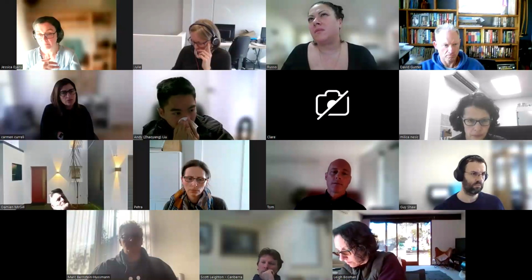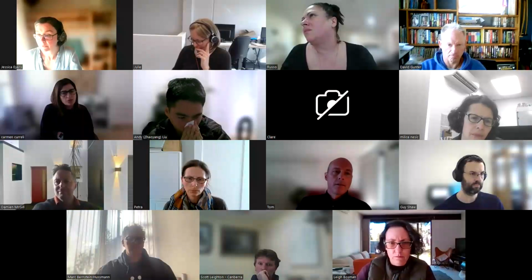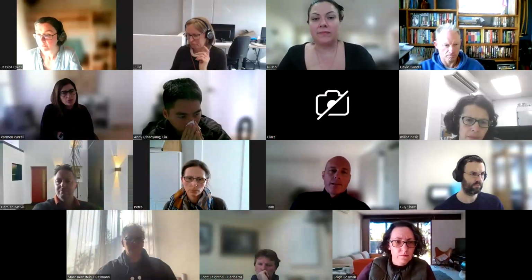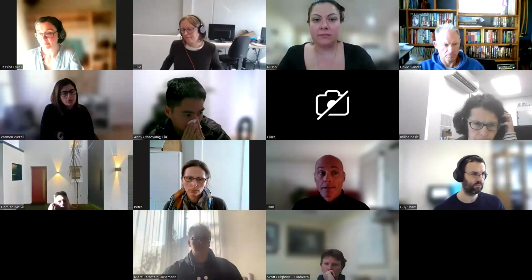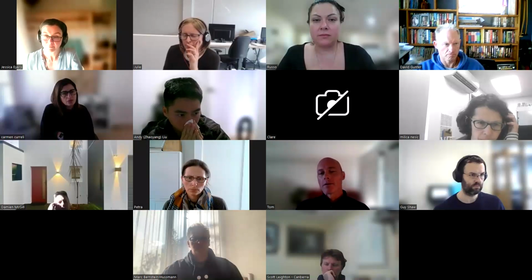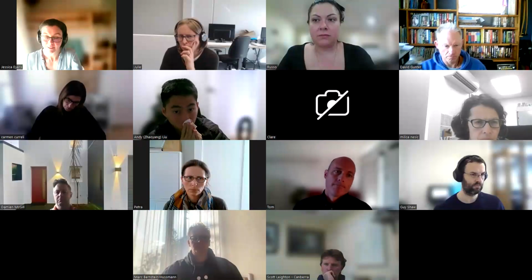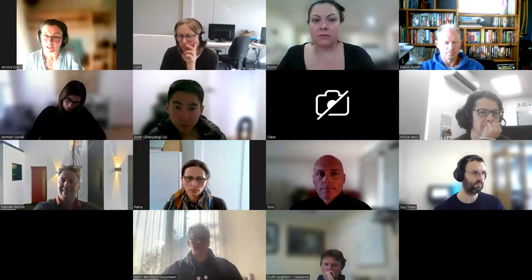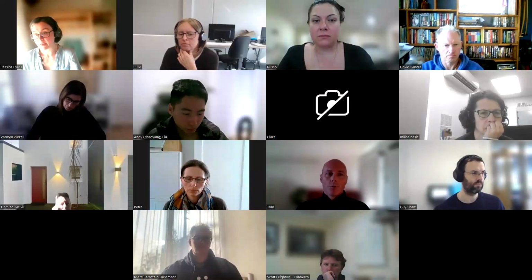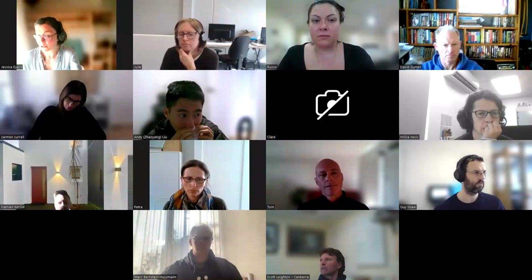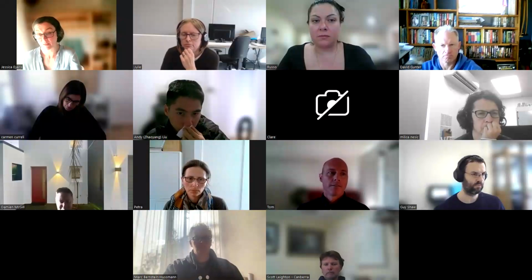Okay, sure, that makes sense. Great. And then my follow-up, because I've had a brief dive into EasyPH, and without reading any instructions, added some data other than through the EasyPH sheet. I'm presuming, with the way you presented it, that makes it invalid as a certifiable EasyPH building. Yes, because then you're essentially breaking the tool. So if there's other things, then I would use your standard PHPP, or you can use a conservative assumption like with the thermal mass.